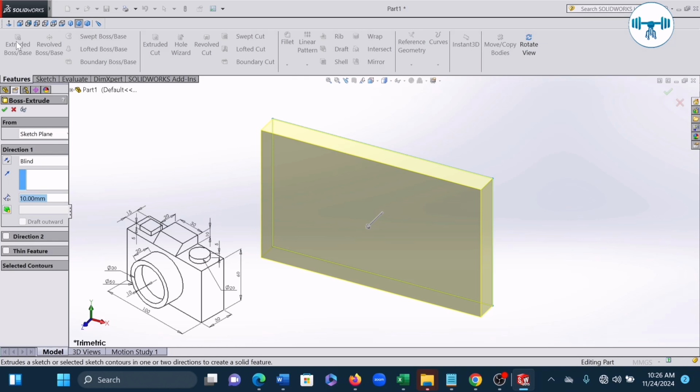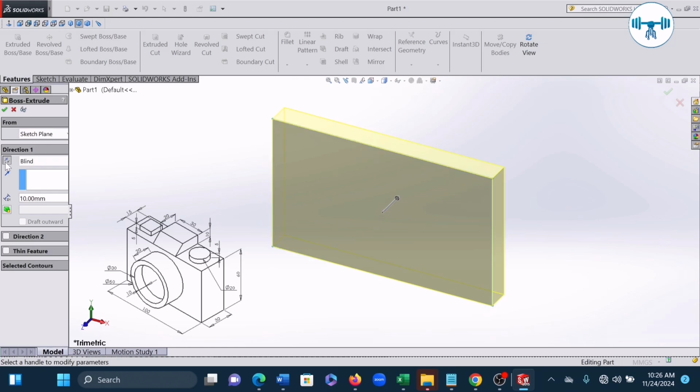So look at my drawing. You see, I'm going to extrude through 30. Okay, I want to change the direction. So look at this thing, direction. I want to extrude backwards. So I want this front to be my base plane. It's not so necessary, but I just want to extrude backwards. So I'm going to input 30, enter.